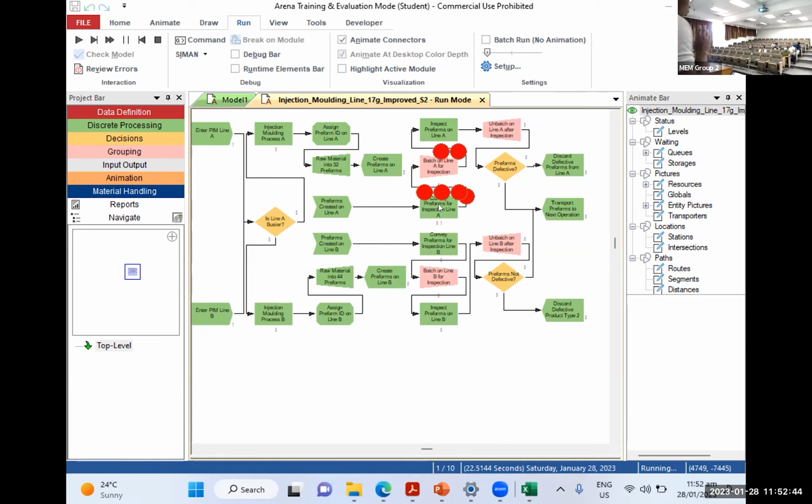And eventually, what this kind of simulation can do is measure all the things that I have mentioned, such as the waiting time, the value added activity, the cycle time, the queue time, if, for example, each particular cell is working with a technician, a machine, or a collection of these things. By doing so, you will be able to understand where the bottlenecks are really taking place, as opposed to where a practitioner, a technician, an engineer may think the bottleneck is.